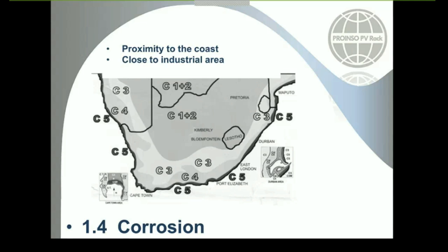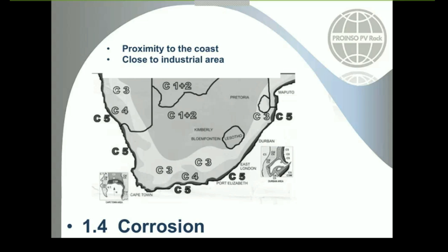It always depends, because, for example, not in coastal areas but in industrial areas, imagine that you have a huge level of pollution, maybe some rusty surfaces could appear even with the anodized coating, but this is really rare, it has to be a high level of pollution, okay? But just to clarify, it is the steel structures that could be damaged. In aluminium, there's not this kind of issue, okay?